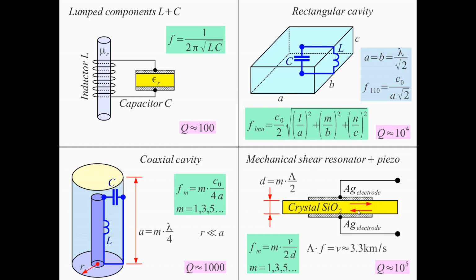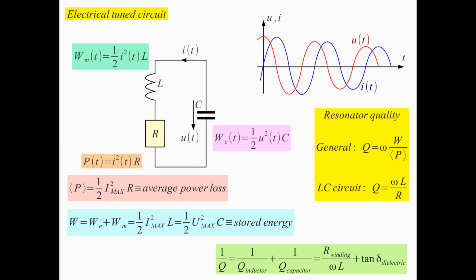So this shear wave resonator has no losses of mechanical oscillation leaking out of the resonator, and if mechanical power is leaking out, we are damaging its Q. The same formula for the resonators is also valid for mechanical resonators. Here it may be mechanical energy, kinetic or potential energy, and here maybe mechanical power loss.